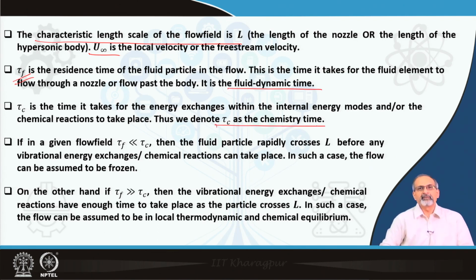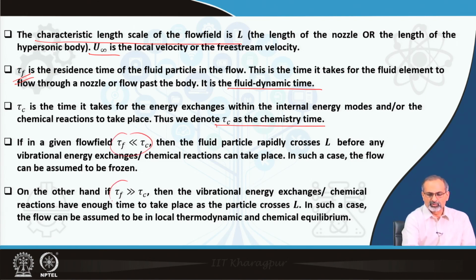Correspondingly, there is the chemistry time, where the energy exchanges within the internal energy modes occur, as well as the chemical reactions get completed, and it depends on how these two times scale that we have to finally take a call whether it remains predominantly frozen, or predominantly in equilibrium, or is going through non-equilibrium. It applies for a CD nozzle, it applies for a blunt body flow, or any other kind of geometry that you can think of. So, these are the primary issues that one has to consider before coming to a conclusion,